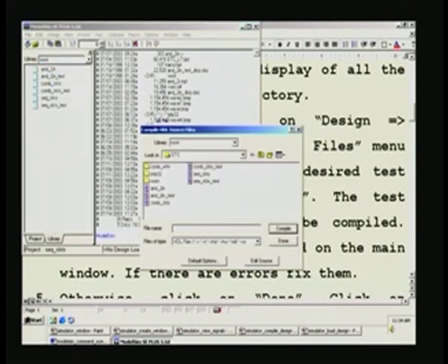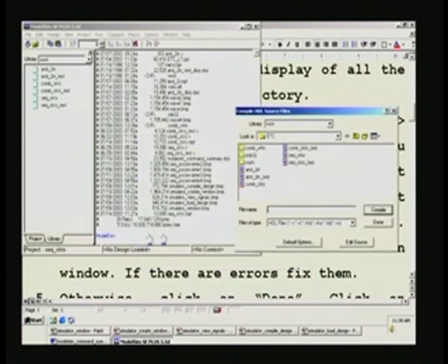Another window opens, we will see a zoomed version of what we have here. Now in this you see all the test benches, including designs, are listed here. For the sequential circuits test bench, you can click once, then it will appear here, and then say Compile. This is one approach. A faster approach is simply to double click this, and you do not have to press Compile. So, I will double click this here, and before that let us see on the left what happens on the window. I am double clicking on sequential_circuits_test.